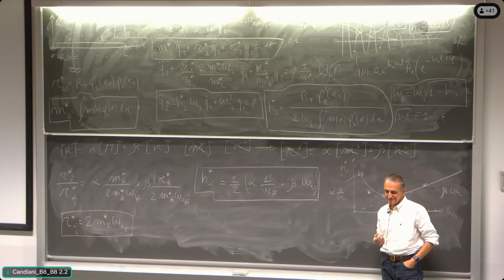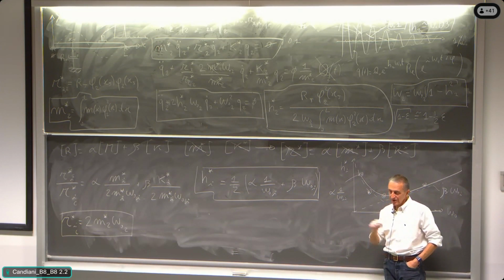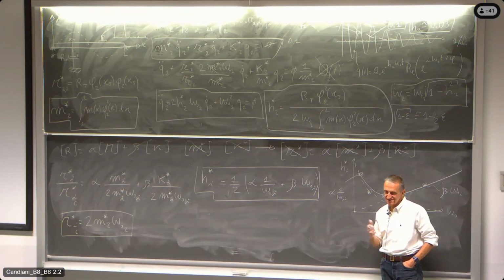The Eurocode is saying that for well-built welded steel structures, the non-dimensional damping that should be accounted for is 3 over 1,000, so 0.3%, and it is saying just that.